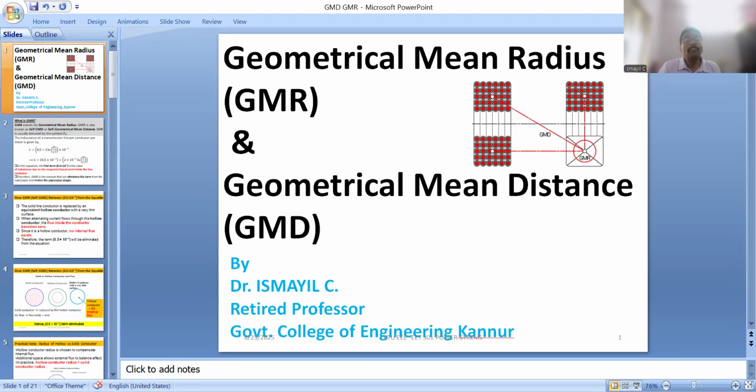So the first conductor in the bundle R phase to the conductor Y, that is from center of first R to center of first Y, it is 5 meter.